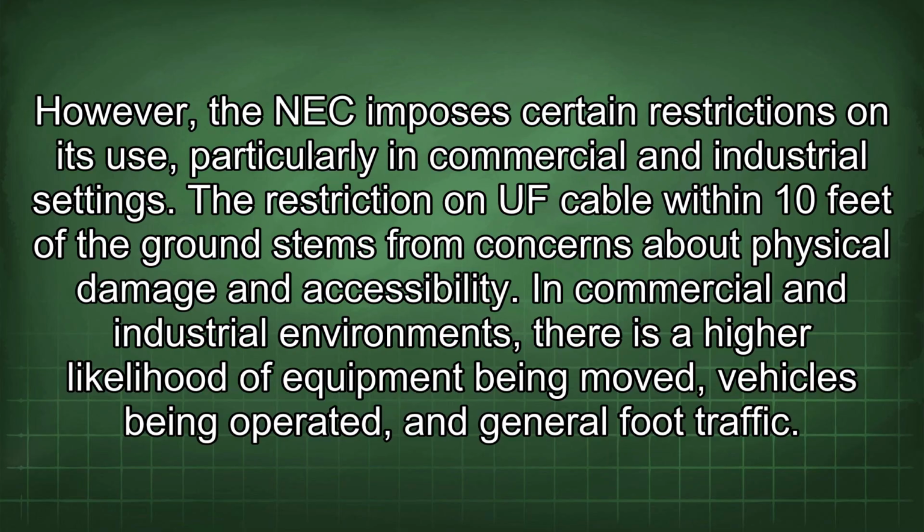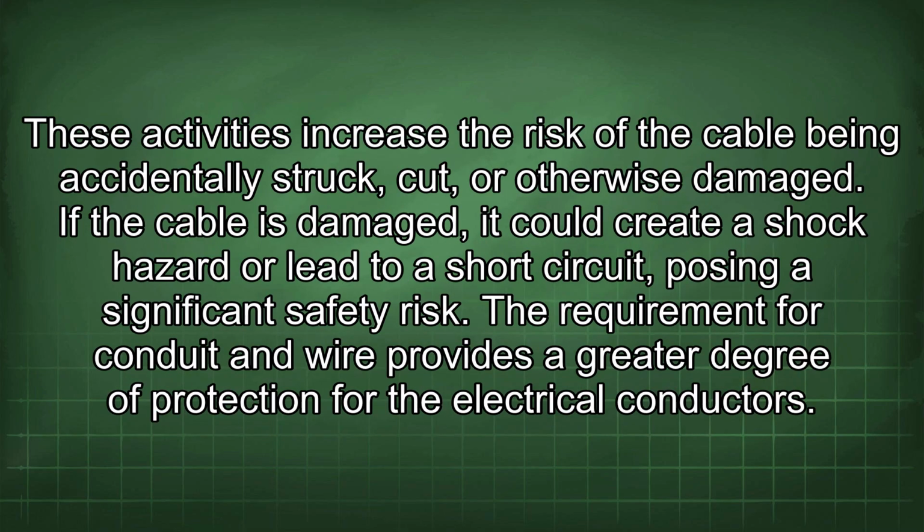The restriction on UF cable within 10 feet of the ground stems from concerns about physical damage and accessibility. In commercial and industrial environments, there is a higher likelihood of equipment being moved, vehicles being operated, and general foot traffic. These activities increase the risk of the cable being accidentally struck, cut, or otherwise damaged. If the cable is damaged, it could create a shock hazard or lead to a short circuit, posing a significant safety risk. The requirement for conduit and wire provides a greater degree of protection for the electrical conductors.